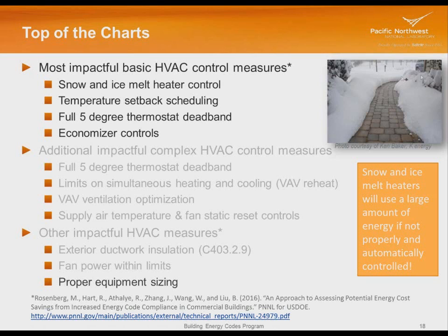If we've got some heaters under this walkway that keep it clear in the winter in our northern climates, that is a system that, if it is not properly controlled, let's say it stays on all summer long, can use a tremendous amount of energy. So not every building has this, few of them do, but I want to point out that if they do have a system, there are some control requirements in the code that you should make sure that they meet. There's some precipitation sensing requirements and temperature requirements so that this unit is not really running when it doesn't need to be.